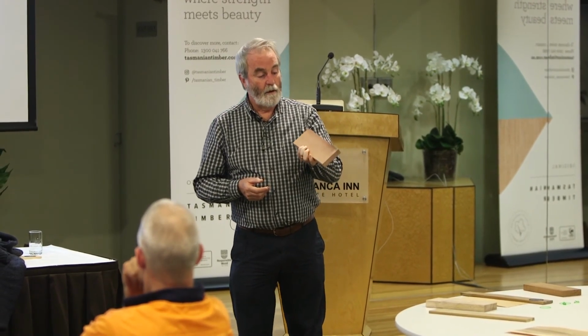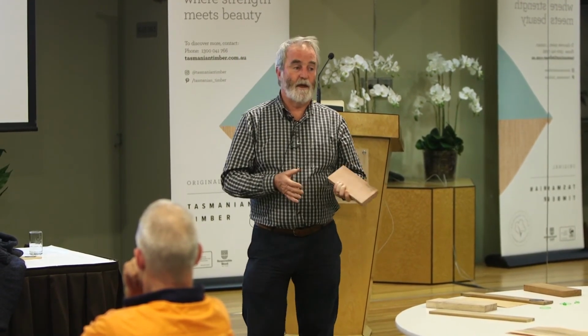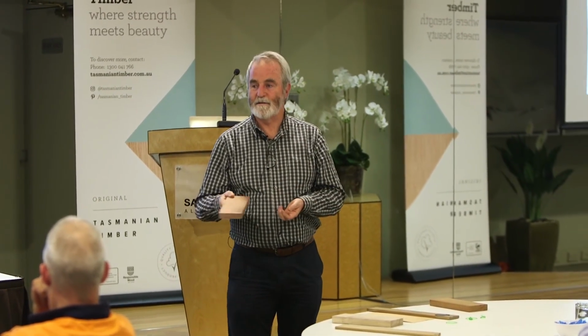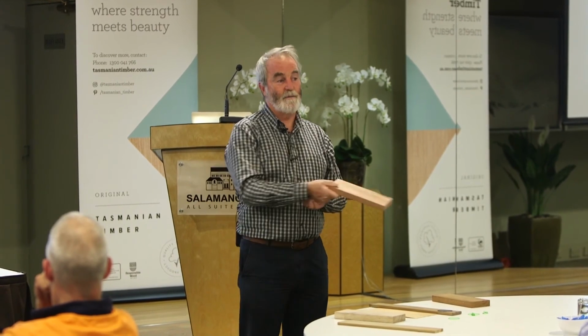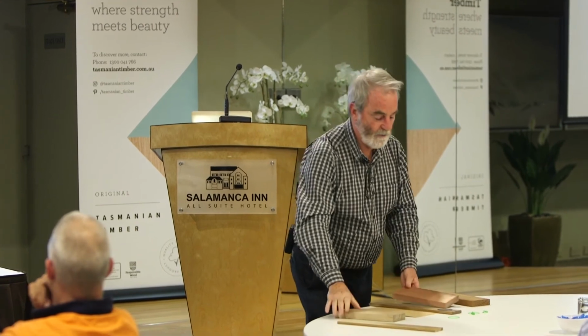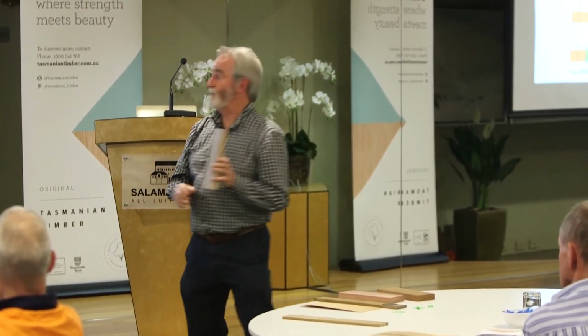So if they are selling it at 11 and it goes to you as a builder and you leave it out in the rain for 3 weeks, then it's not going to be 11 when you put it into the job. So you monitoring that moisture content then becomes important.